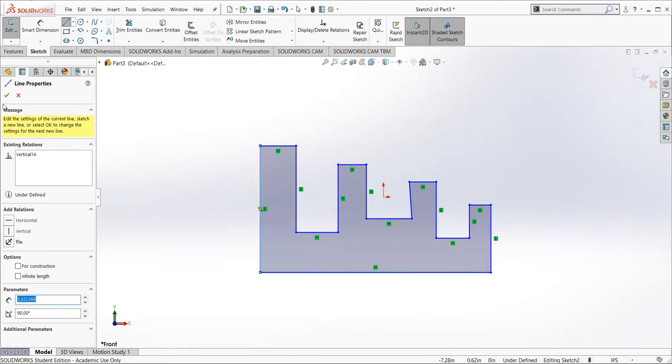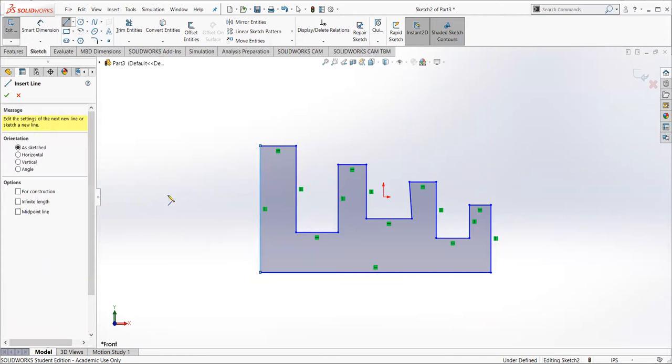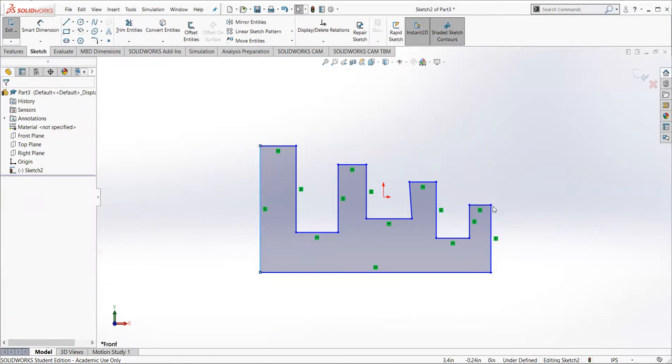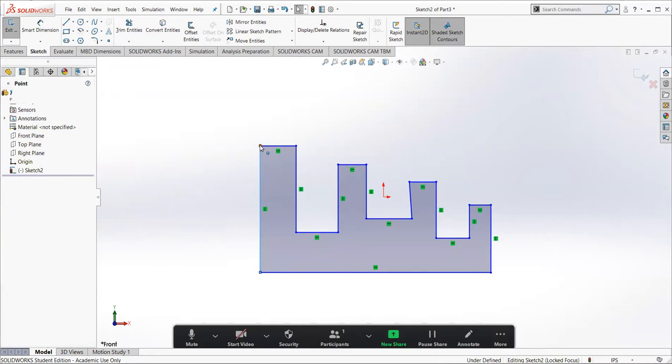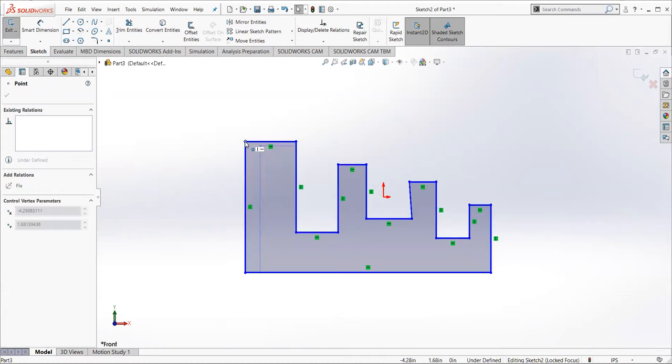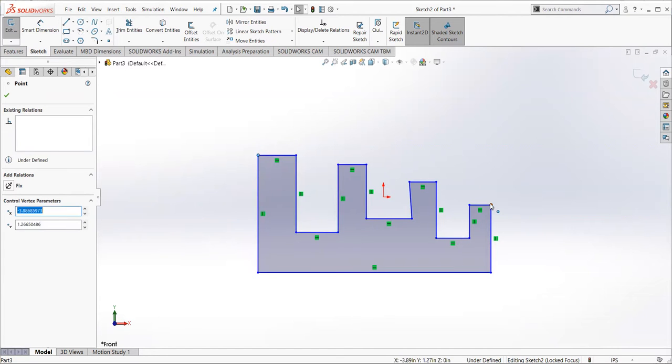After you finish your drawing, you can click yes. Make sure you have created a region by clicking in one of the corners and trying to drag it. So you will notice that you have created a region, which is very important later when you do the extrusion.